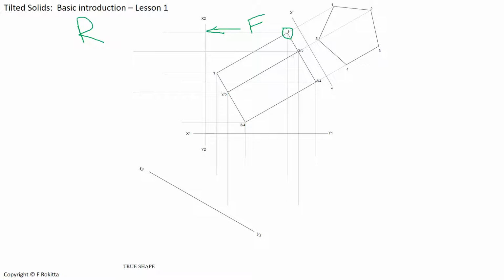But it is your choice whether or not you want to do these projections now or only once we start doing the measurements for our right view. But please keep in mind that they are also light construction lines and that they are perfectly horizontal and projected from each of the corners to the right view.